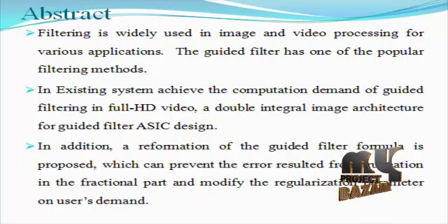Filtering is widely used in image and video processing for various applications. Recently, the guided filter has been proposed and has become one of the popular filtering methods. In this paper, to achieve the computational demand of guided filtering in full HD video, a double integral image architecture for the guided filter ASIC design is proposed.